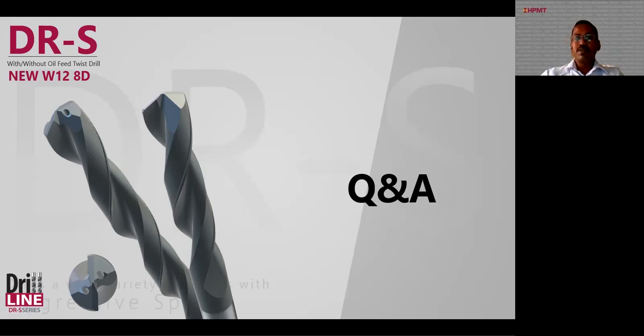Okay. Thanks, Mr. Idris, for your question. Yes, 8D drills, or even 3D, 5D and 8D, anything with diameter 3 mm and above, no need to go for pecking. You can do direct drilling. Pecking is normally applied for very, very small diameters, for example below 1.5 mm or below 1 mm.